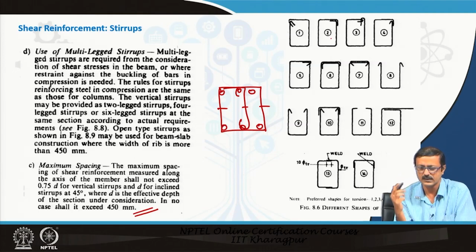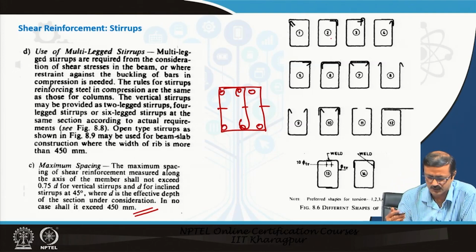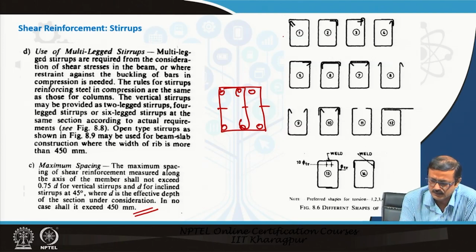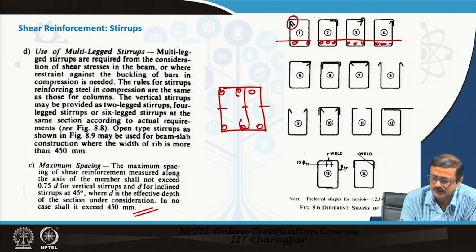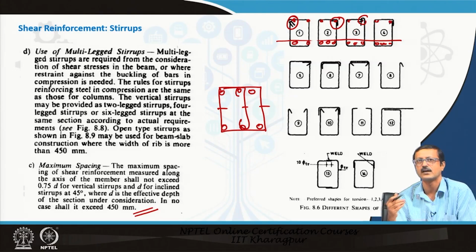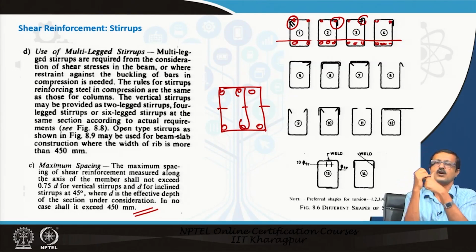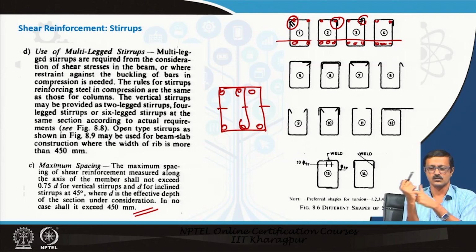Now, one thing is very clear, if it is a simply supported case, the tension comes in the bottommost zone. So, those are your design number of bars, but stirrups are actually held at the top. There will definitely be two top bars at the corners. So, the stirrup will be held and bent in the top direction, which is not the design part, that is the compression zone of the concrete. The steel associated with the holder or those hooks is very important.